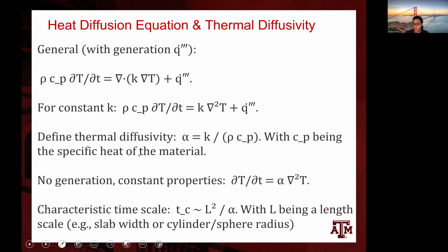Now, if we have heat generation, then the Fourier law is what we call a constitutive law, but to solve for the temperature under different conditions, we use a balance law. In this case, it's the balance of heat. Heat is a form of energy, so energy is conserved. So we use balance laws to see how things are going to conduct or diffuse, while at the same time accounting for the fact that energy is conserved. The balance law would look something like that.